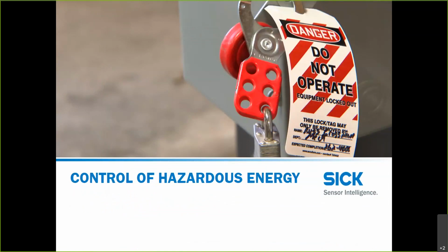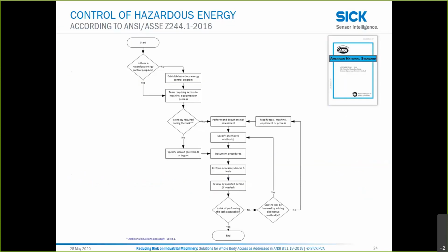These are presented in a hierarchical order, and so what that means is that the standard recommends which ones should be considered first versus which ones should be considered later through the process. So we start with control of hazardous energy, simplified as lockout tagout, but it's more than just lockout tagout. It's how do you control the hazardous energy that could result in an unexpected restart of equipment. So we know OSHA has guidance. That guidance is from 1981-82, from when some machines were much simpler. They were either running at full speed or they were completely stopped.